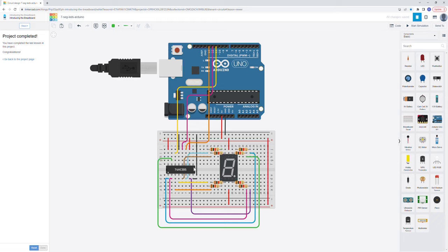When an LED is lit, the exact pin on the shift register forces 0, low voltage, and current flows via the specific resistor into the shift register's exact pin, and this lights up the exact segment in the 7-segment display.